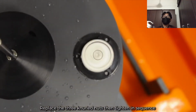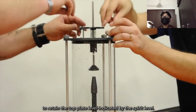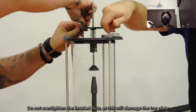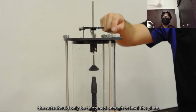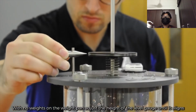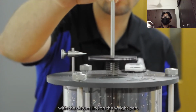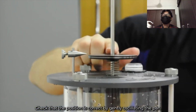Replace the 3 knurled nuts, then tighten in sequence to retain the top plate level, as indicated by the spirit level. Do not overtighten the knurled nuts as this will damage the top plate. The nuts should only be tightened enough to level the plate. With no weight on the weight pan, adjust the height of the level gauge until it aligns with the datum line on the weight pan. Check that the position is correct by gently oscillating the pan.